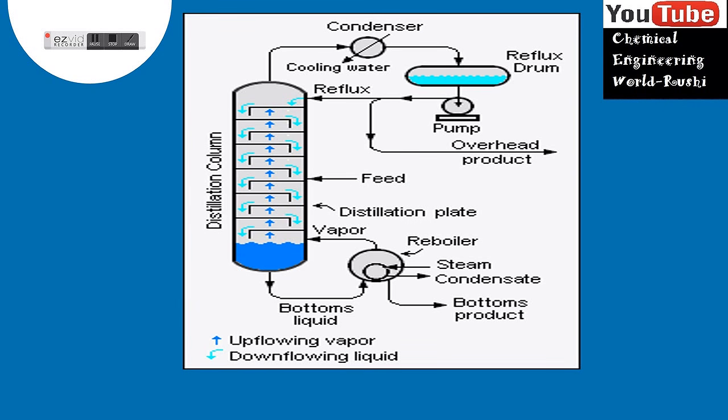Figure shows a schematic diagram of an example distillation column or fractionator. The feed enters the column as liquid, vapor or a mixture of vapor-liquid. The vapor phase that travels up the column is in contact with the liquid phase that travels down. Column distillation is divided into 2 stages: rectifying stages and stripping stages.